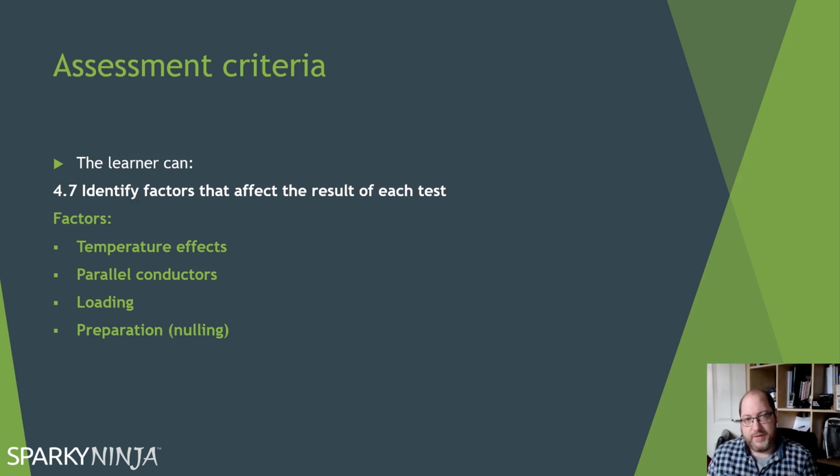So parallels will have an effect. We need to remember two things with parallels. From the initial verification point of view, we must remove them, or do the testing before we introduce them. From the periodic inspection testing point of view, we have to understand them, not accept them, but more work with them.